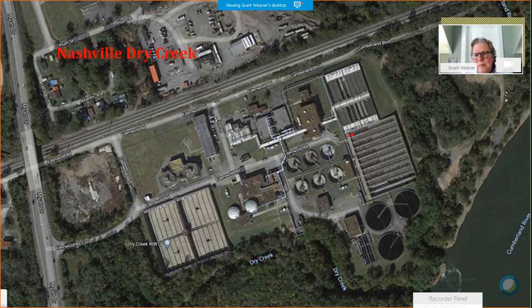So we thought, well, it's a plug flow plant with all the flow coming in here. Maybe we're losing all of the BOD and there just isn't enough to drive the nitrate removal. So there is a step feed valve down at the far end. It hadn't been operated for a number of years, so that was a little problematic, but they worked through that and they opened that step feed valve so that a percentage of the flow, I can't remember the percentages, somewhere between a quarter and a third of the flow was being bypassed entirely around that first zone.